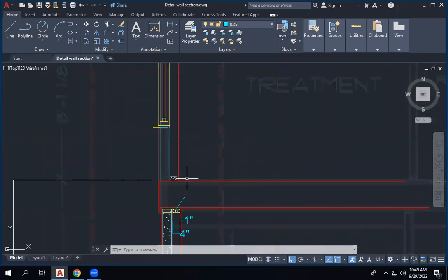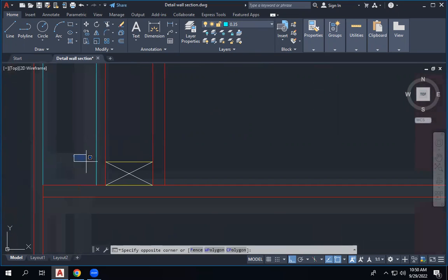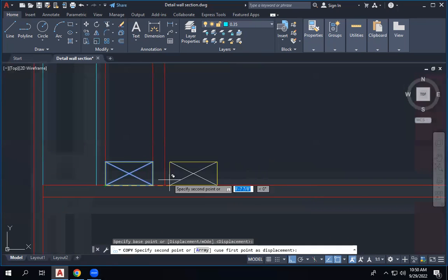And also remember now this is the truss that we have here. And you need to put another layer for the finishes. How are we going to do the finishes? This is a truss. We have trusses at certain distances, so in between two trusses there is actually a void. So what we do is, if we have two trusses, we put some sections, timber studs or steel sections, and we put a plate, like a timber plank, and then we do the finish on top of it. So there will be 3 layers. One is the same as this timber stud. We have something like this here.